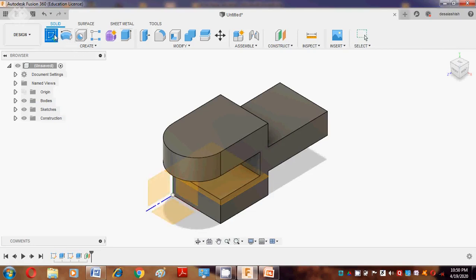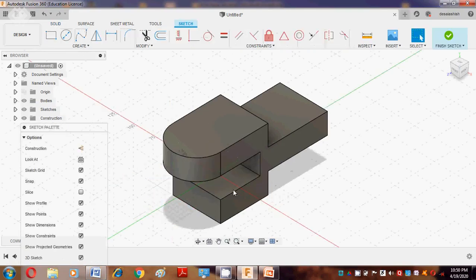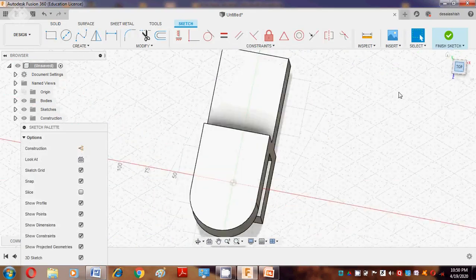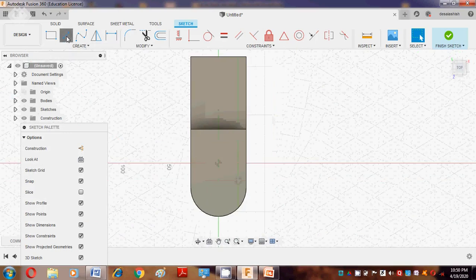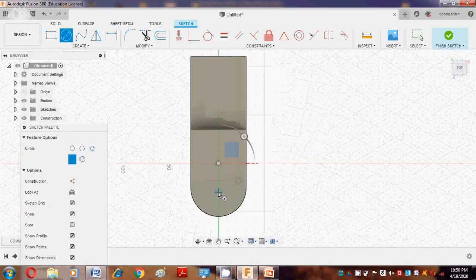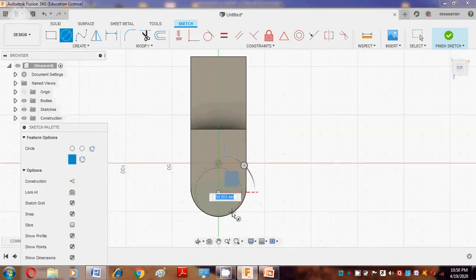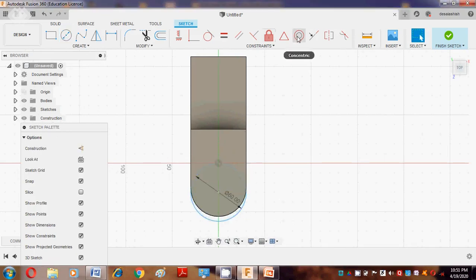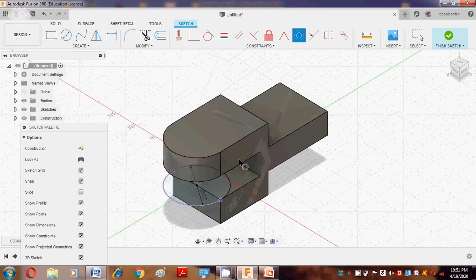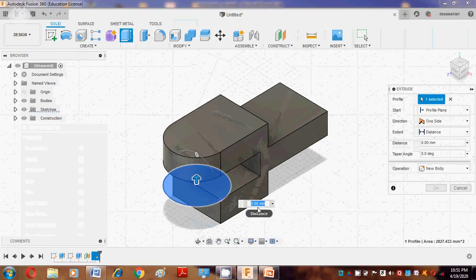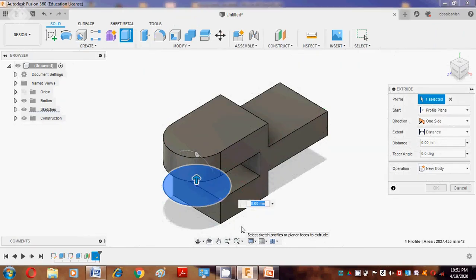After that, go to the sketch, create sketch, and then plane selection. Then again go to the circle, and then we find the point here. So you can put the value 60 here. Then go to the concentric circle. Then we select these two points. Then say OK. Then you can extrude it. Extrude is by pressing the E button. Same here, then minus 25.